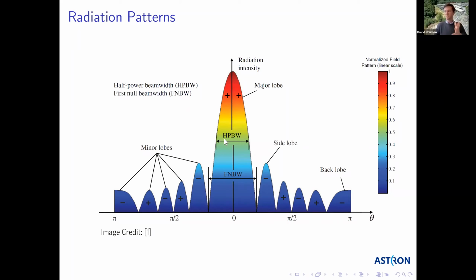So this is mostly when we've designed an antenna, you go to the radiation pattern and you look, did I achieve my half power beam width? What are my side lobe levels? These are the typical quantities that you'll be looking at.